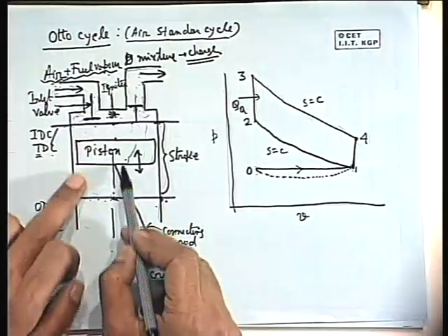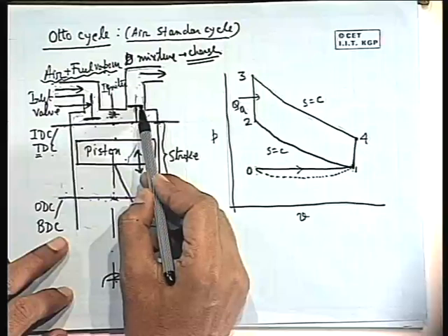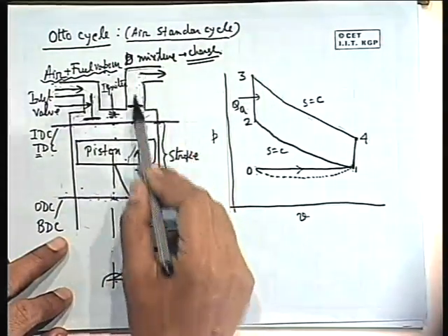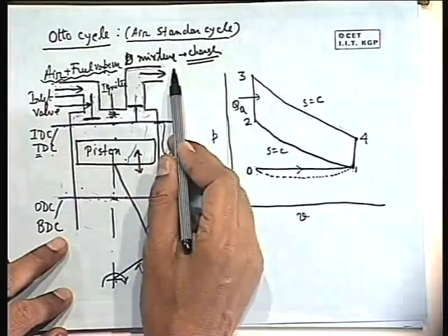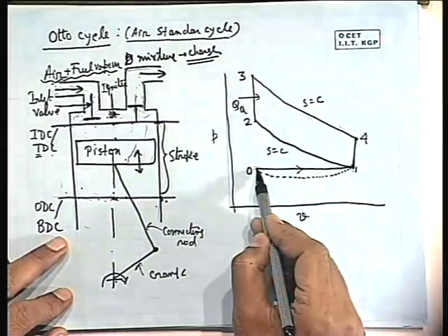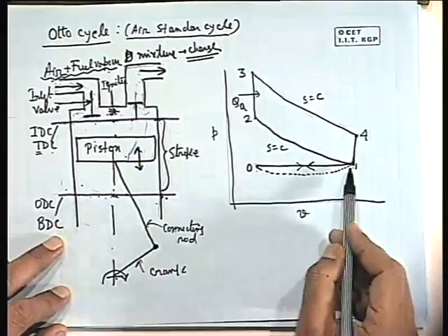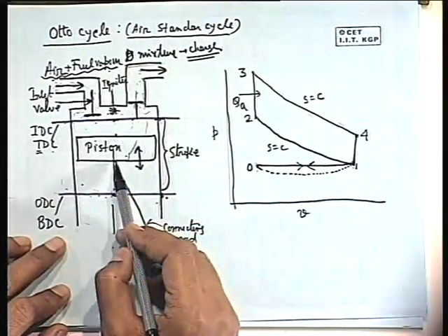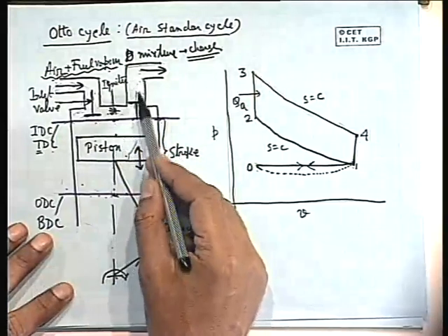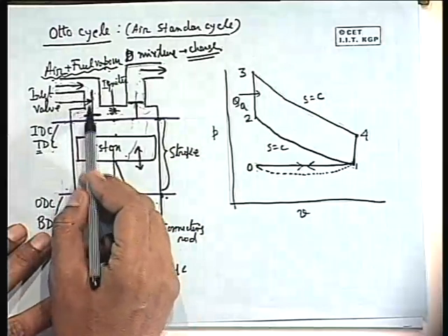Why? Because when you push this, there is a compression, so pressure should rise, but this is an open system. That means the mass is going out. So you understand, exactly this is an open system, the mass is going out, so if we conceive it as a closed system, we can conceive it as a constant pressure exhaust. That means constant pressure discharge of the air. This is because the increase in pressure is being nullified by the exit or efflux of mass, the way the decrease in pressure was nullified by the intake of mass.